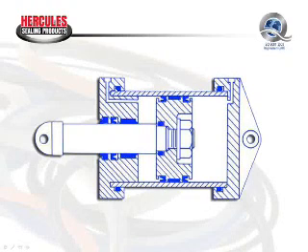So this O-ring under pressure, because it's elastomeric, will be compressed, and then it will be released as the pressure releases. So there will be some slight movement here. The same is true underneath the piston. There will be some slight movement of the O-ring within this space, but it will be very minimal, with no relative motion involved. Our dynamic seals are the 2 U seals on the piston and the U seal on